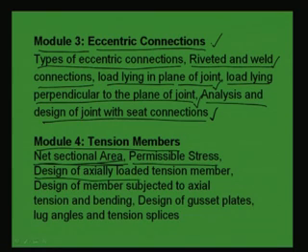The design of axially loaded tension member, design of member subjected to axial tension and bending. That means, first we will discuss the design of axially loaded tension member, where only axial load is there, then axial load along with bending, and how the design will change, that we will show.